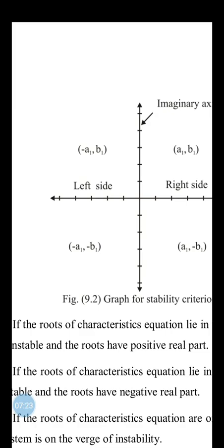If the roots of the characteristic equation are on the imaginary axis of the plane, then the system is on the verge of instability. So we will discuss the Routh-Hurwitz stability criterion, which is the first method to discuss for the stability characteristics.